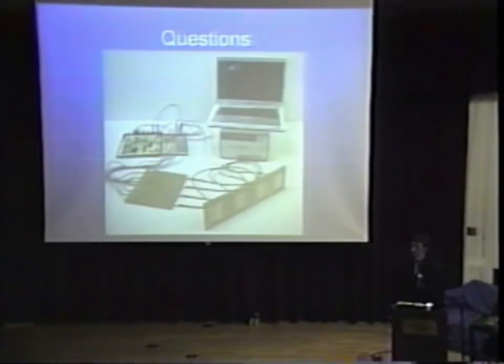Okay, the question is, you'd like to see an example of how you might want to use this. For something like a communications network, for example, you could modulate a signal into it using amplitude modulation. Because I got about 1.4% bandwidth out of it, using a low frequency signal, you could modulate that into this device, transmit it, receive it with another one, and then demodulate it. So you could actually communicate with the high frequency signal.